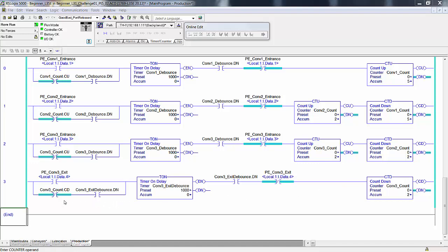The one thing that you may miss that is an absolute must: remember that it's the advent of the count up bit that resets this rung. Well, there's no count up instruction in this 4th rung, rung 3. There's only count down, so you have to use the count down bit. Now here you could probably use the countdown in these two and it would be okay, but we'll stick with keeping this code looking the same.